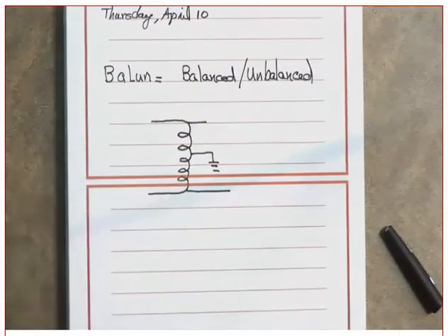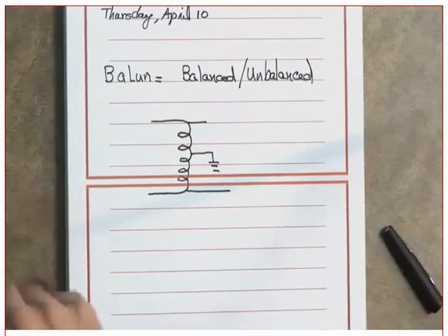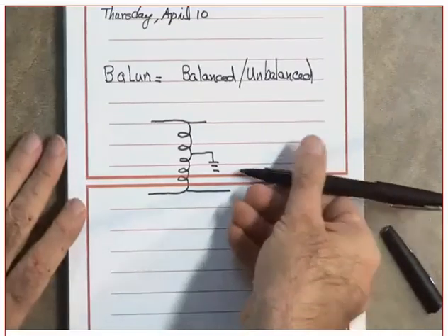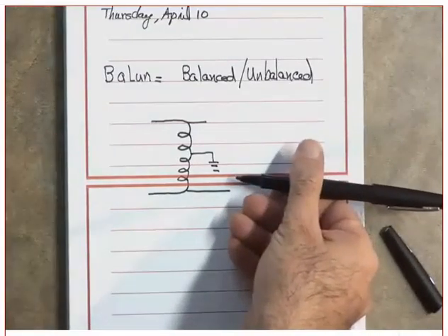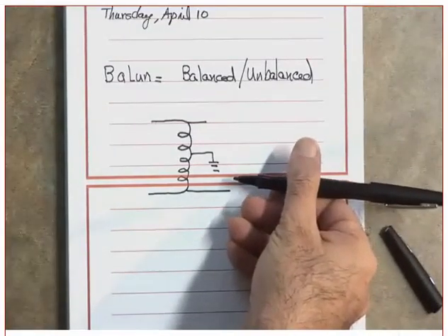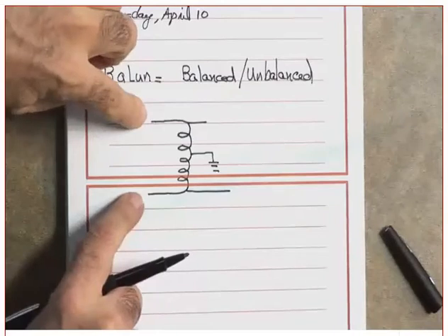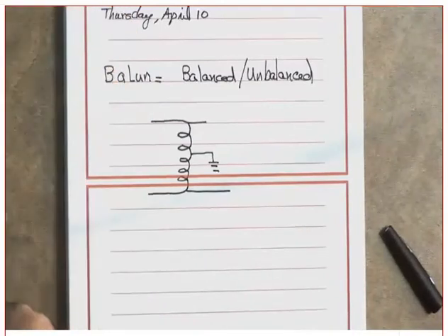Whereas in here, there is no ground. So I use positive and negative. Of course, you can use that at the input to change a single-ended to a double-ended. Which means what? You take the input in here from the single-ended low-noise amplifier, and you take the outputs from here to drive the differential mixer. Professor? Yes. 5 minutes left. Okay. Just heads up. Did you get it?